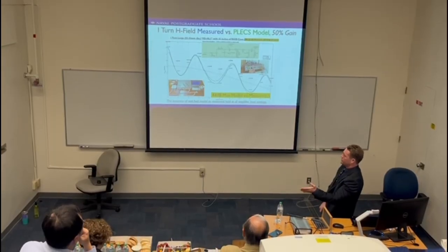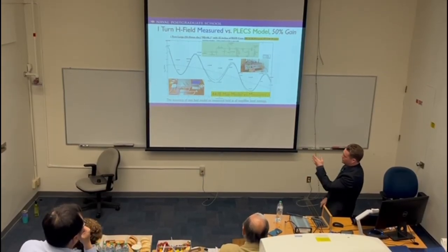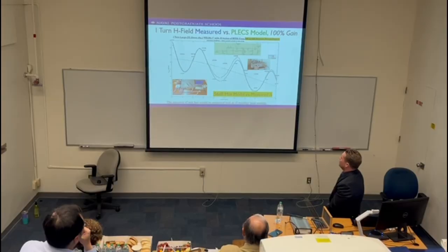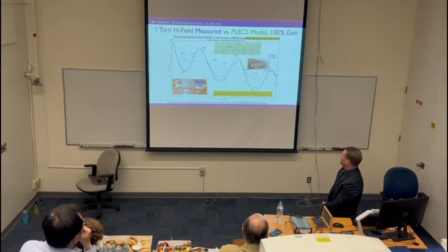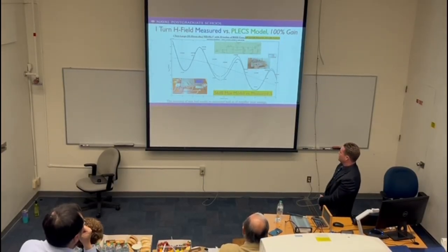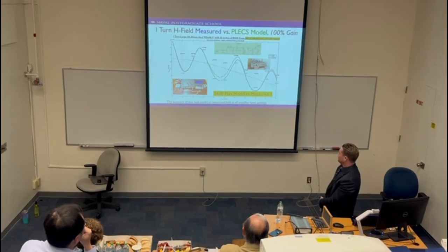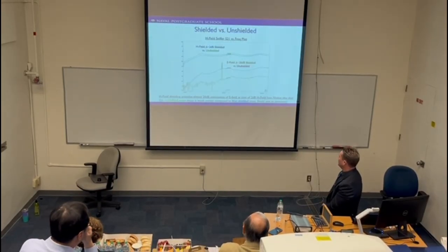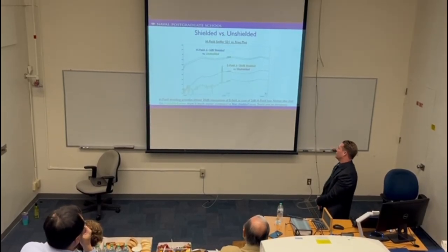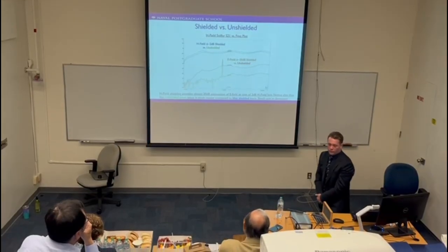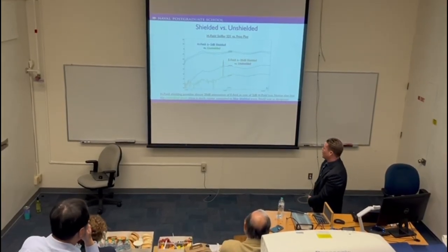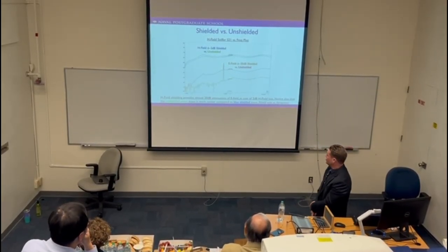Just tell me what the frequency is and what your signal generator is going to be, and I'll tell you what your H field is going to be. And here's the one turn at 100% gain. Again, you can kind of see the noise starts getting a little interesting, and it held. And then here's another, just to confirm what we spoke of earlier with the H field and the shielded injector.